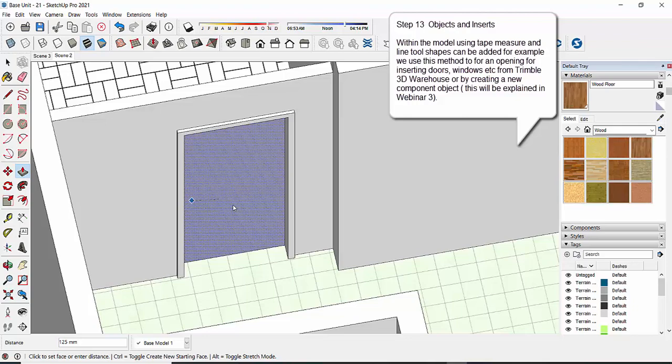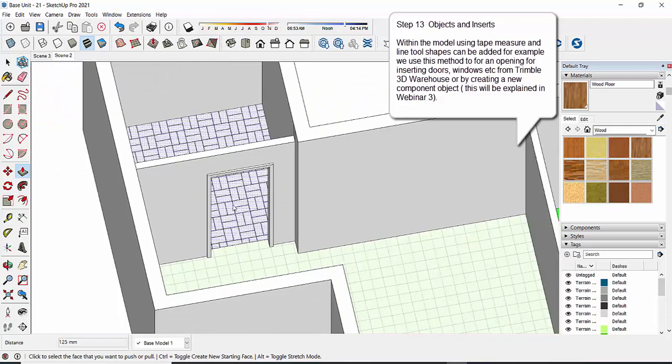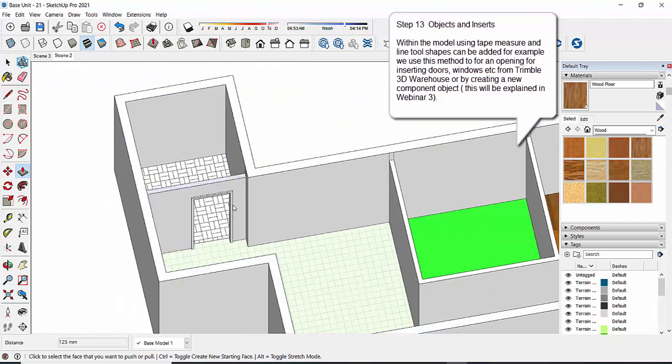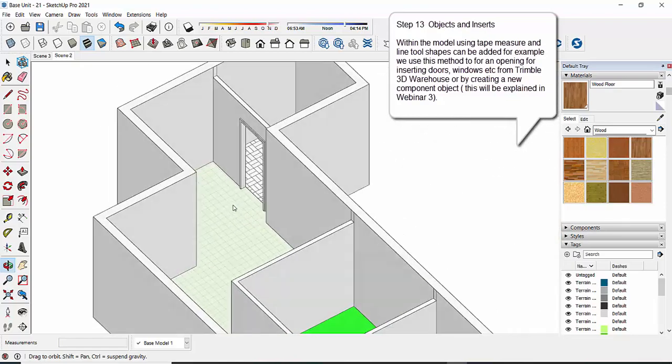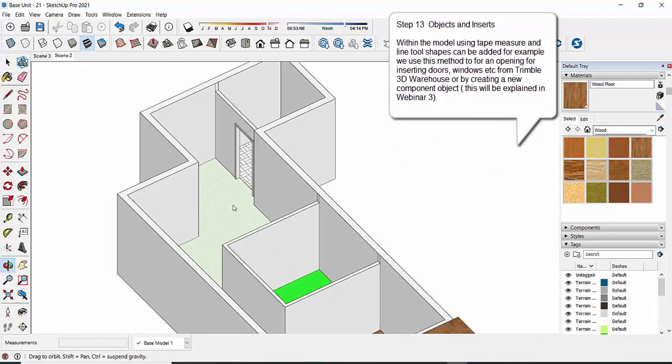We can use it to cut an opening. Literally by using the push command, we can simply push an opening into our walls. So when we bring in doors and windows into our model itself, we have a predefined opening that we can actually extend within our model itself.